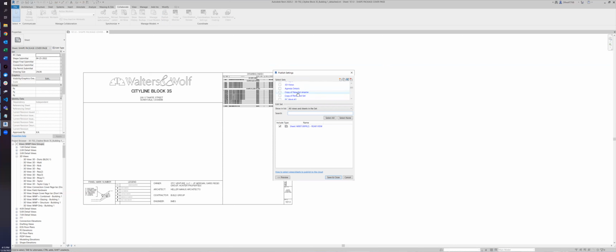So we see our new copy sets. Copy new set rename. We added these two sets. And then new set rename, the original one. You can see it added these views, so our WB and our wall section and our partial second floor. And that's how you use the BIM 360 Upload plugin.